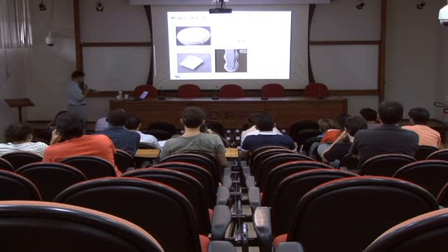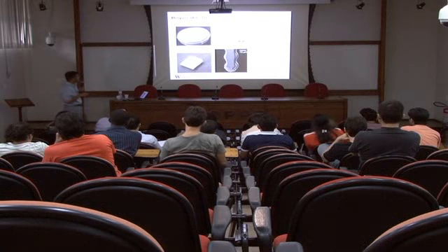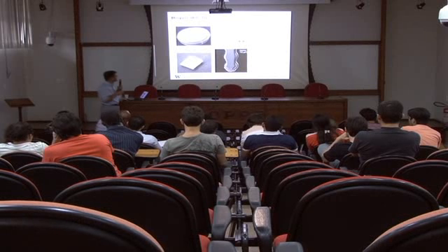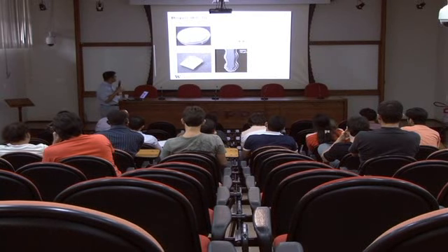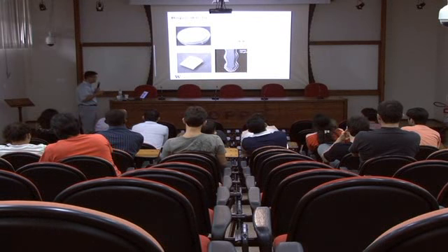For this purpose, we fabricated small tips. In one wafer, we can make about 400 chips, and each chip has 5 microtips. This chip is installed in a coupon, and the whole thing is disposable. If we look at the tip end, it has a wiggled shape to generate a large electric field.